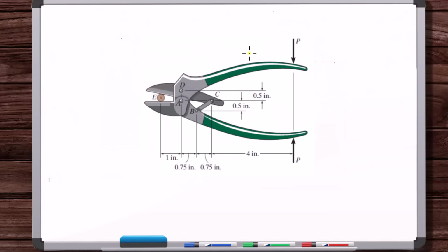No. Okay, here's a planar free body diagram. The geometry and the loads are symmetrical with respect to the center plane of these shears, right? The shears are symmetrical with respect to a center plane, and the loads are symmetrical as well. Someone's pressing on the shears to cut this piece of this twig. Are these all of the forces? Well, let's look at all of the exposed area. Is there any other exposed area that's contacting something in the environment? Well, the hands here, and so that's why they put these two forces, the hands.